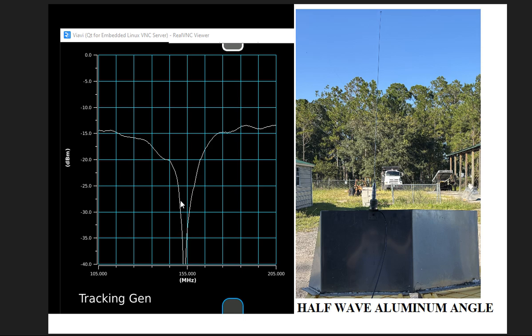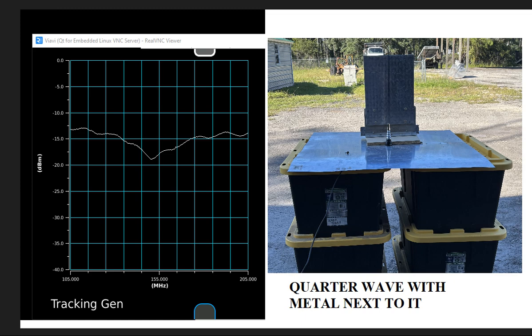it has got a little bit of a tighter bandwidth, and not as much as it usually has. You can see the V is really sharp here. And it might have shifted over just a little bit on the resonant, but not much. But overall, a much better performer as far as the half wave is concerned, if you can get the tuning right. So, all right, let's look at the next example, which is what happens if you get an antenna mounted